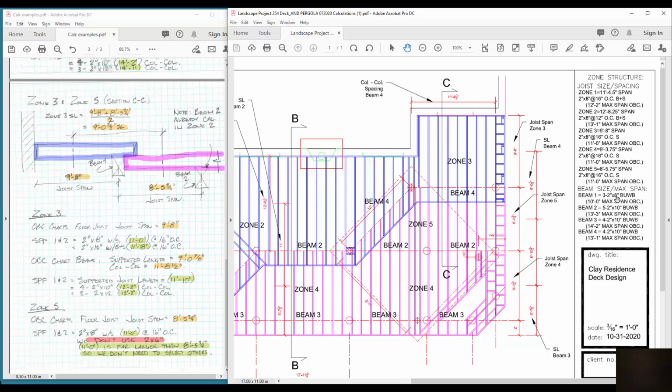For me to go to three 2x10s, I could. It would be far beyond what I need. So that's why I selected a 2x8 in terms of a beam. And I'm okay with that because the joists are 2x8. So with any cutoffs, or when I do the orders, I'm ordering only two sizes, 2x8s and 2x10s, and most of the 2x10s are for the beams.